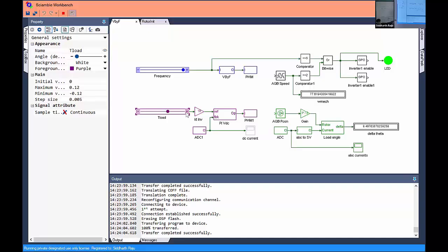Otherwise, there is no torque in the system. The rotor would come to a stop. At steady state, the speed is the same. It's just that the rotor is slipping behind an angle, not in speed. That's quite important. In transient, the speed will reduce, but it will come back and settle down to the same synchronous speed. Okay, so going back to the animation, we started at 1200 RPM. At the end of the day, we settled back at 1200 RPM. That's the only option.